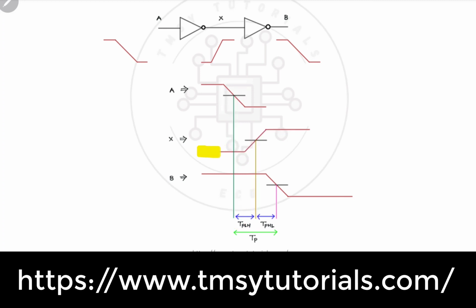Now this X will act as an input to the second NOT gate, and this is the output that we are getting. Again at the 50% point, draw a vertical line. Similarly at the 50% point for B, draw a vertical line. Now here, if you observe, B is falling from high to low, so that's why it is TP-HL, high to low.